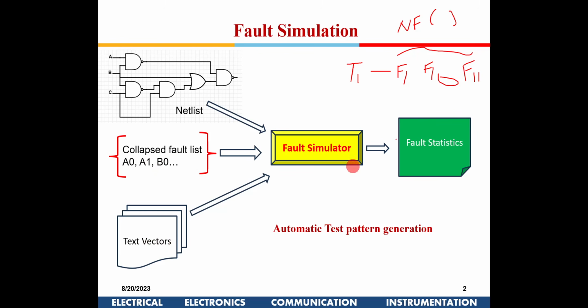That comes from the logic simulation. If there is no fault, the output z should have some value, it could be 0 or 1, and when I give a test vector t1, if the circuit has these faults, it will have the complement of this value. If it is the same, then obviously these faults do not exist. So the fault statistics would be a list where I have test vector 2, and say only fault 2 can be detected with that.